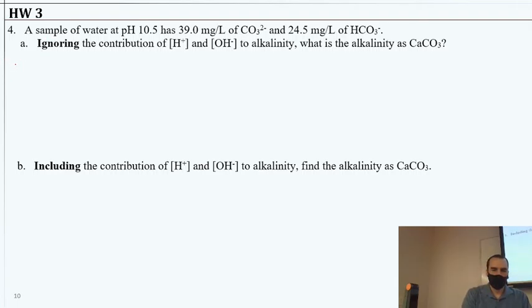So just as a quick reminder, if we take a look at the alkalinity, and in the parentheses here, denoting that it's either milliequivalents per liter or it is as CaCO3, essentially what we're talking about is we've already accounted for the charge differences. So this is going to be equal to the HCO3 minus plus CO3 2 minus.